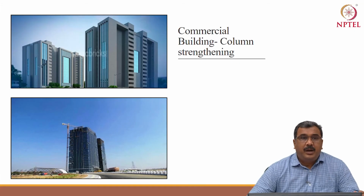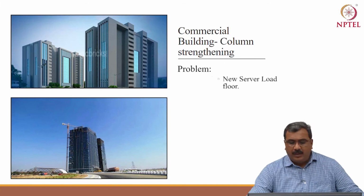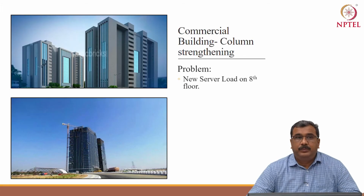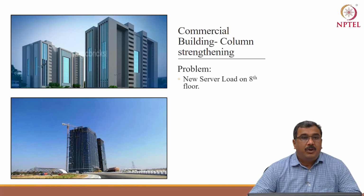When they had constructed up to the 7th floor and the 8th floor was under construction, the 8th floor was sold to a company in the IT sector. They were supposed to have a large server placed on the 8th floor slab, and this additional live load was not considered in the original design.